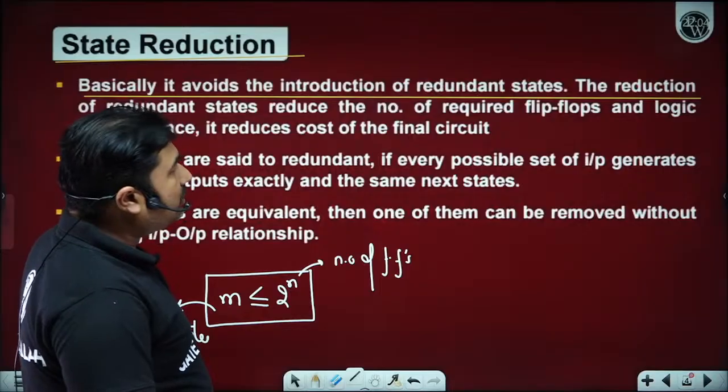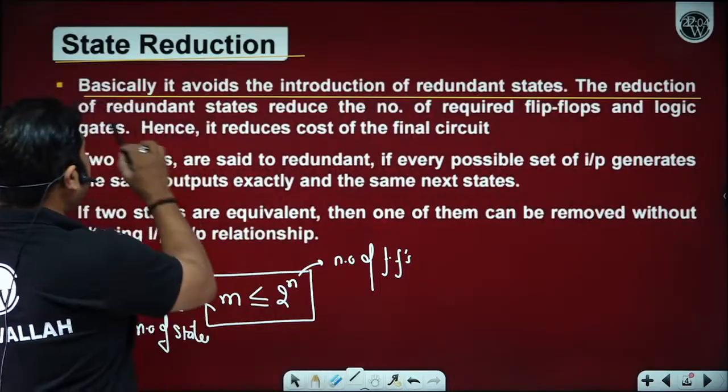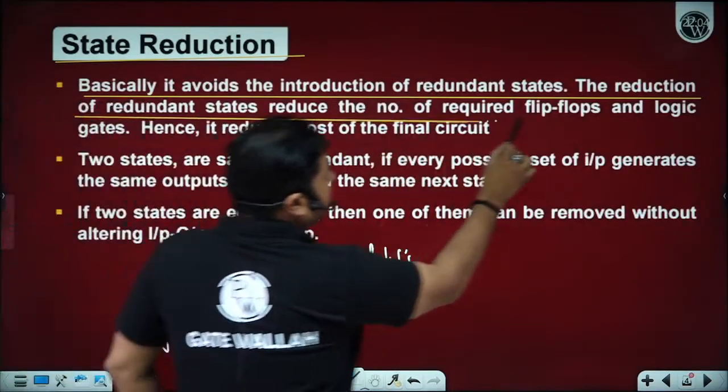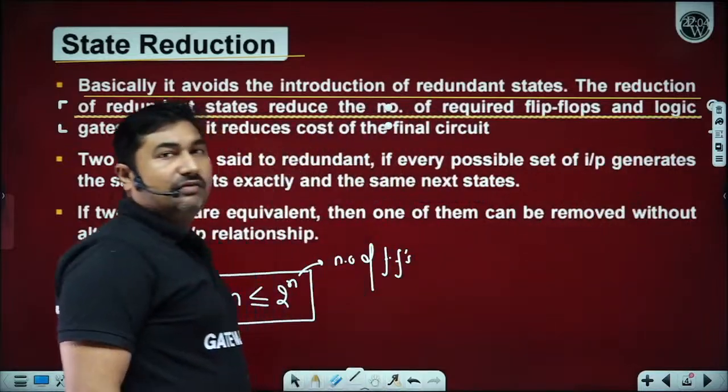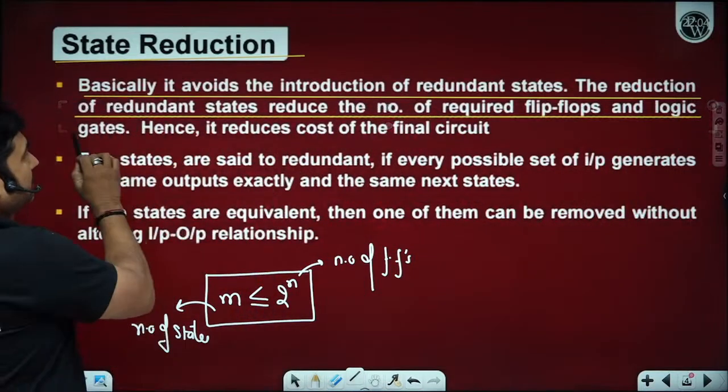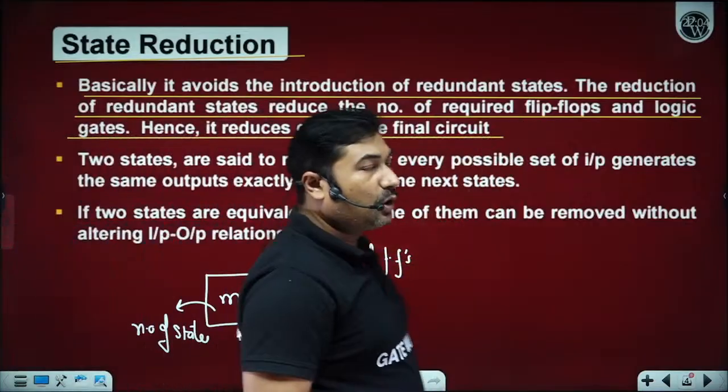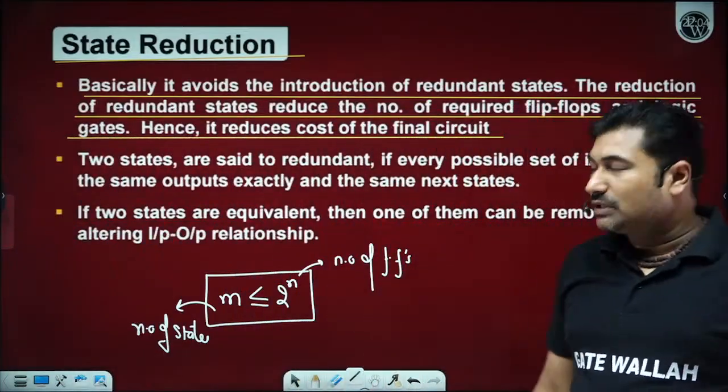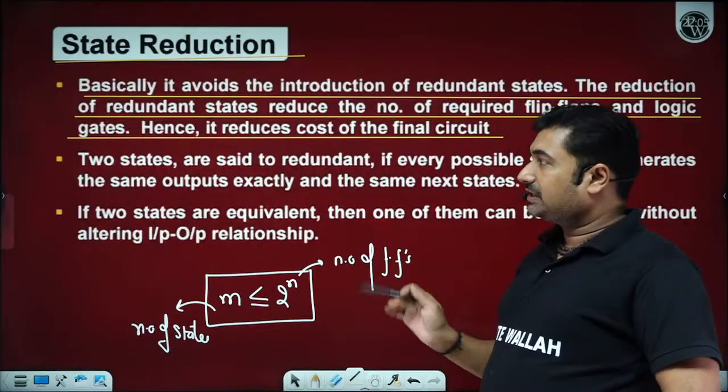Basically, it avoids the introduction of redundant states. The reduction of redundant states reduces the number of flip-flops required and the logic gates. Hence, it reduces the cost of the final circuit. So now we know the purpose of state reduction.